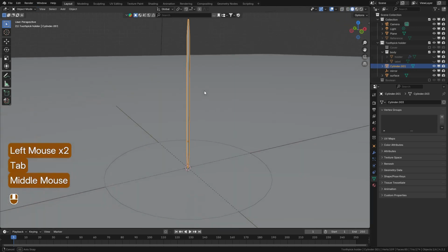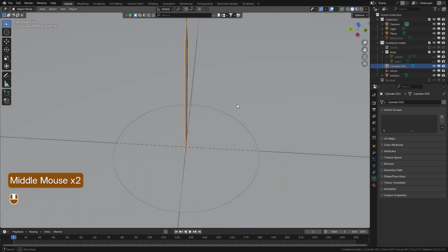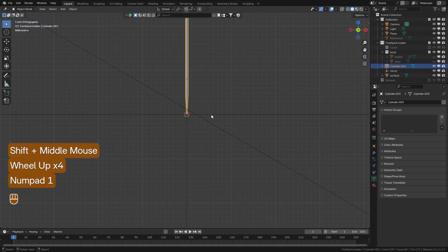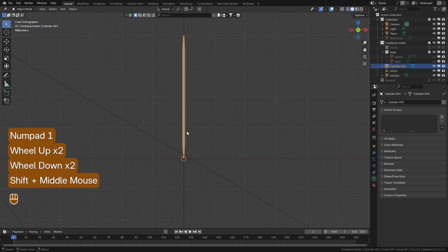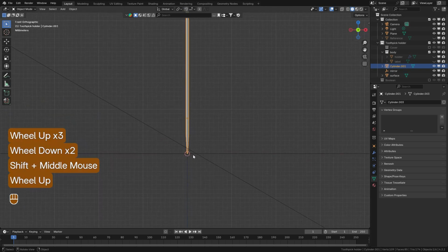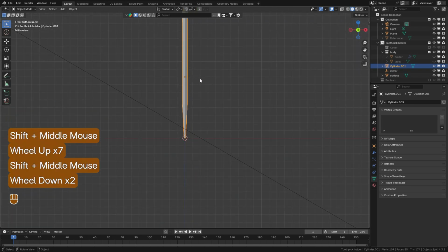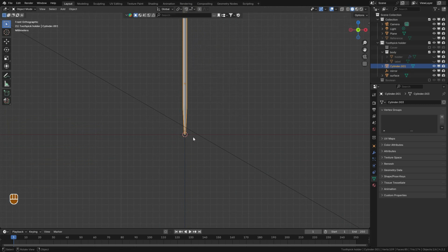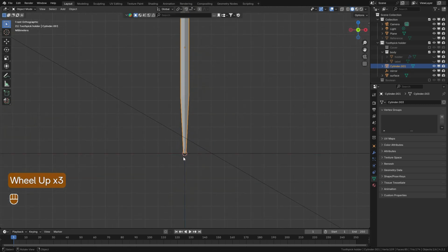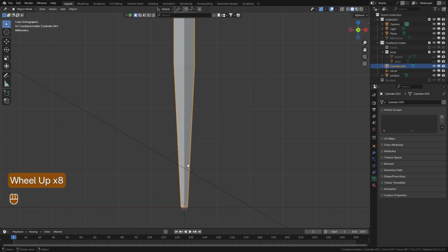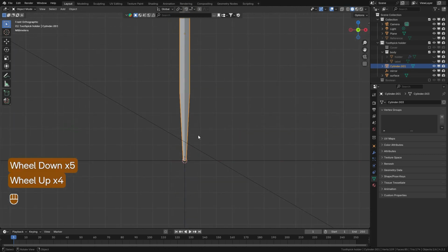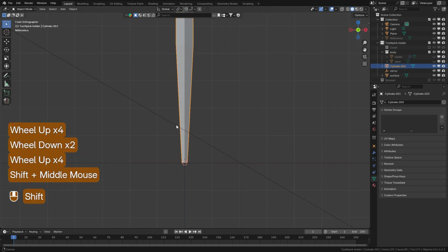Go back to object mode, and there we have a normal toothpick, and this is our toothpick. All right, now we want to move this origin point where it's rotating from. Instead of rotating from here, to be rotating here. This is important for how we are going to spread our toothpicks around.